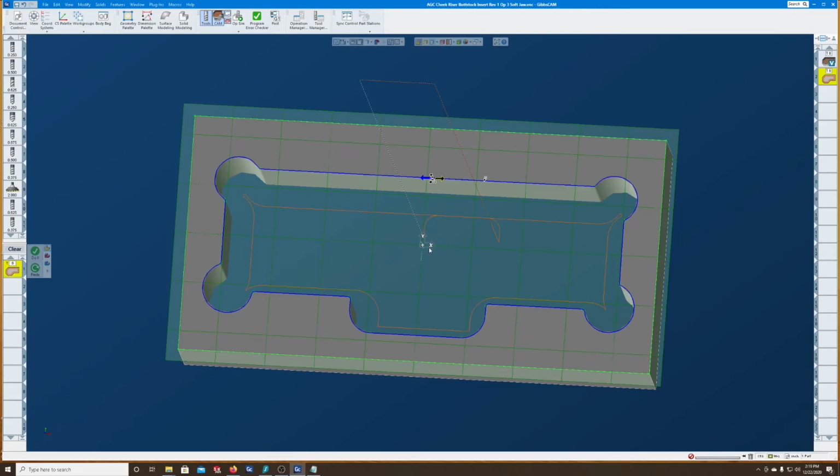And every CNC machine from different manufacturers has what you could say is a slightly different dialect. Down in Alabama, we speak a little differently than up in New York or up in Canada. And CNC machines from different manufacturers are the same way. They have slightly different types of G code that the machines prefer. So basically, we have a couple different machines that we use, and we'll select what machine we're going to machine the part on and then generate G code.